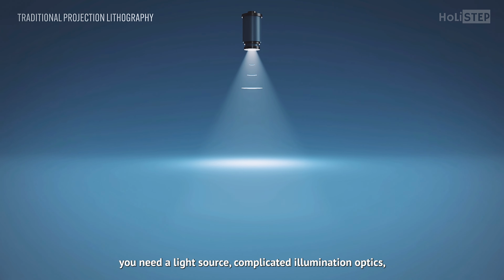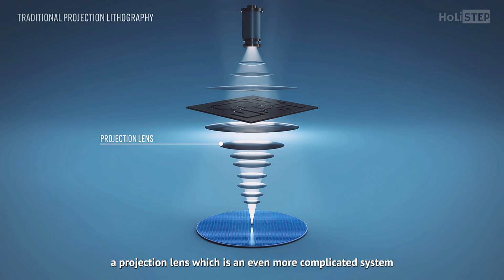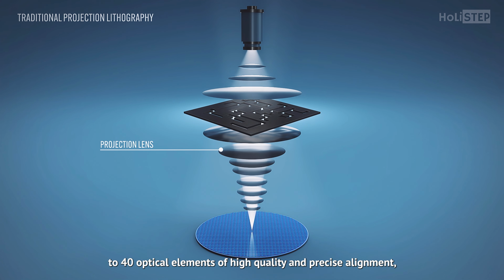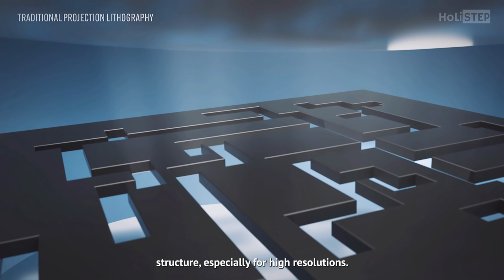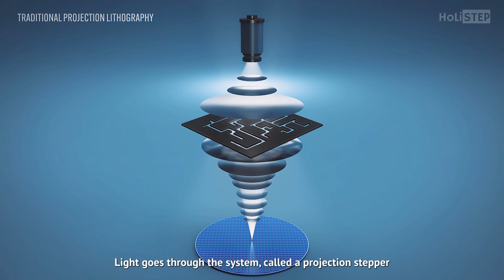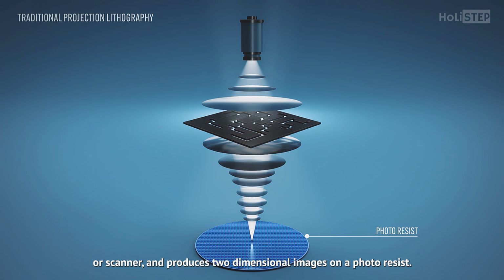In traditional projection lithography, you need a light source, complicated illumination optics, a projection lens, which is an even more complicated system that can consist of up to 40 optical elements of high quality and precise alignment, and a projection mask that has an extremely complicated structure, especially for high resolutions. Light goes through the system, called a projection stepper or scanner, and produces two-dimensional images on a photoresist.